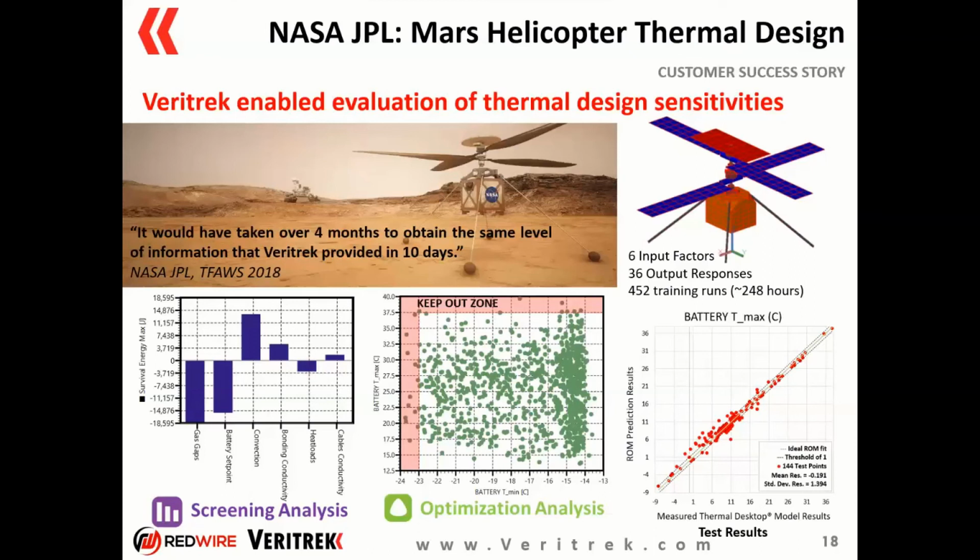Let's see, there's 2 other questions. Examples have shown thermal only models. Is this also compatible with fluid or mixed thermal fluid models? Just the same? Yeah, absolutely. If you recall, the very first video that we saw from the NASA Crew Exploration Vehicle, that was actually a thermal fluid system. So it had thermal radiators, but it had a pump fluid system going through those radiators that had different working fluids. So certainly can handle both thermal and also thermal fluid Thermal Desktop models.